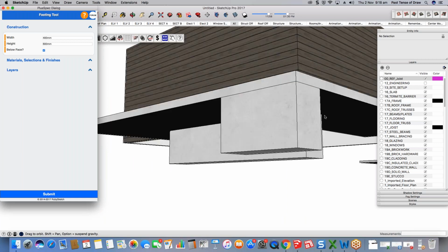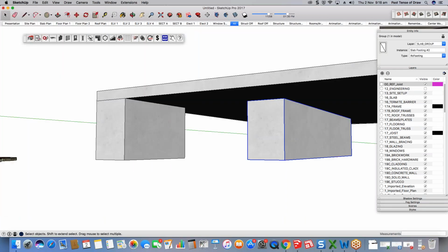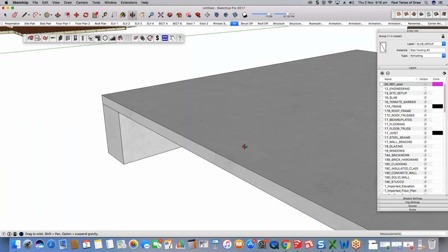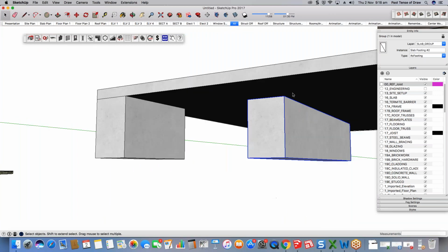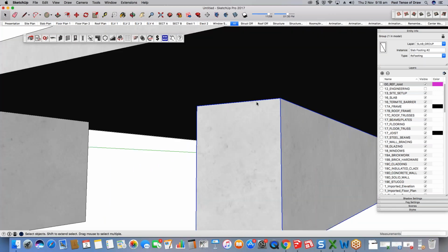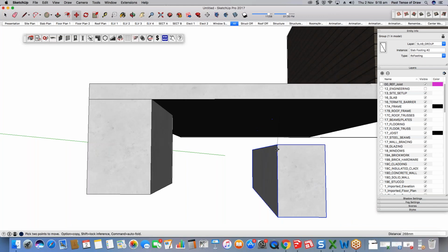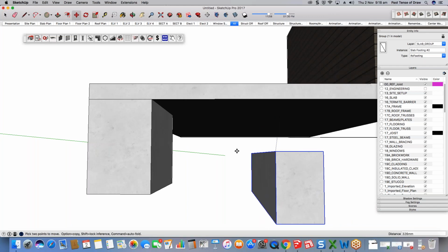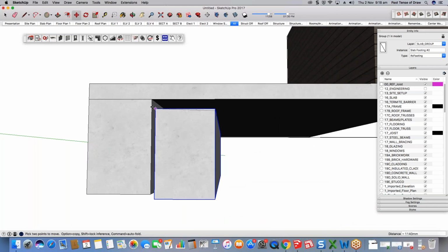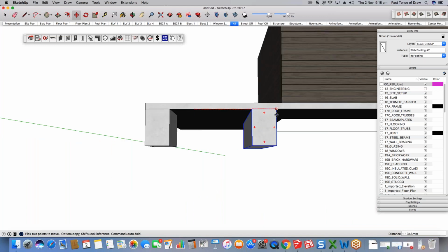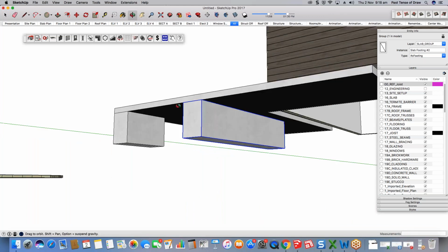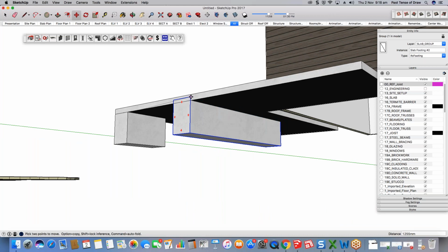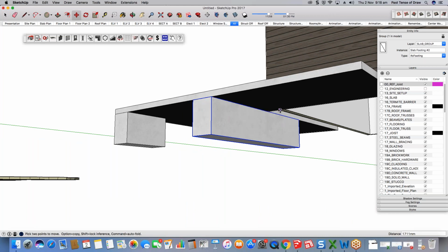And these are standalone items too. So when you draw your footings, because you've drawn them as a separate piece, it means that when you left click and select them, and everything will turn blue, you can use the M for Move on your keyboard, and you can move it around. You can reposition it. So if you change your mind, it's never really going to be that difficult to modify the structure. This enables you to go to a very high level of detail and continuously change your mind as your design progresses.